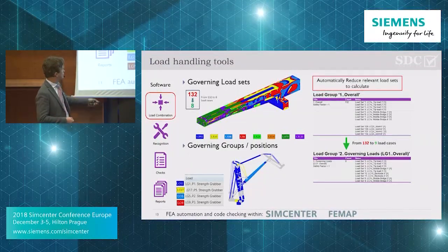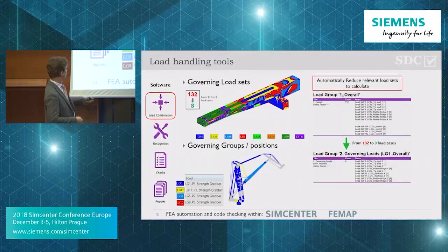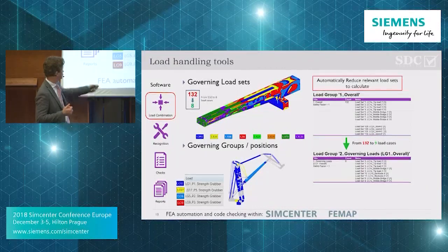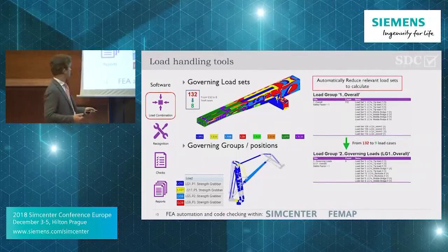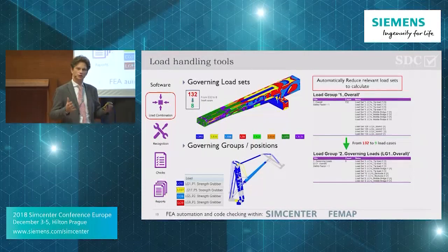For example, here you can see that we set positions P1, 2, 3, 4 and 5, and what the worst load cases are. For large parts of this example, it is either P1, the inward position, or P5, the outward position, and the intermediate load cases almost do not appear, unless only for this boom situation here, where a slightly smaller position was important. So you can get a quicker overview with these tools.